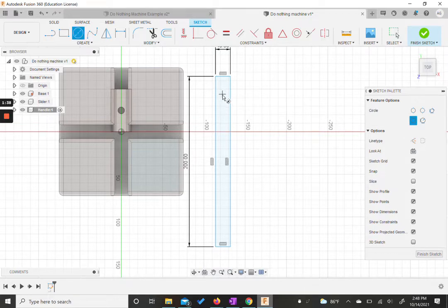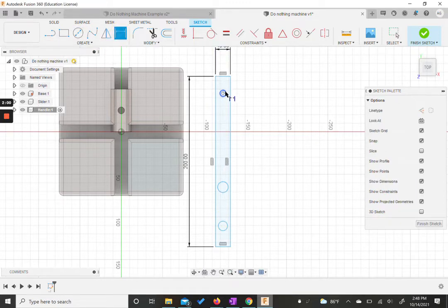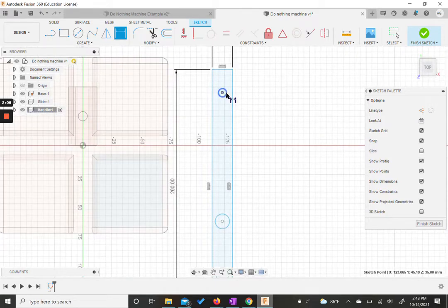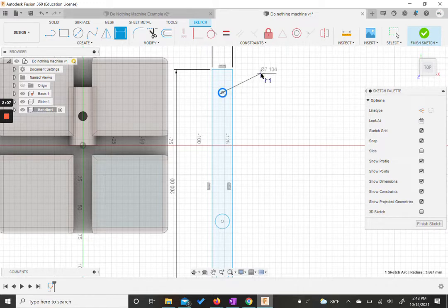which there's a couple ways we're going to do this, but I'm just going to make my life easier. I'm moving my cursor up to the end so that it's centered, and this circle, well, we'll show another constraint in a second then. So centered, one kind of down here, and then one kind of down here. Okay, I'm going to dimension one of these, and only one. Oops, if it's letting me select. Come on, there it goes. To be 8 millimeters. All right, and then I'm going to use my equals constraint to make my other circles the same size.